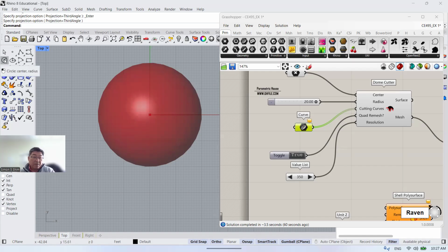and you can use this circle curve. You could click this and drag and drop. If you want to move it, you can move around here by holding down this arrow, right? In case you cannot see this, this gumball should be on. You have to turn this gumball on and off.